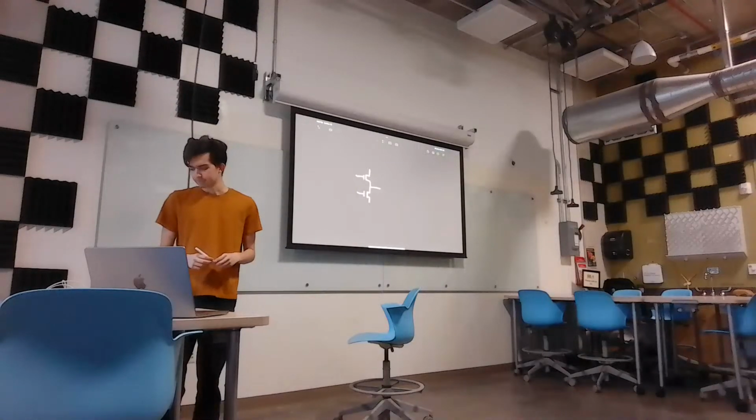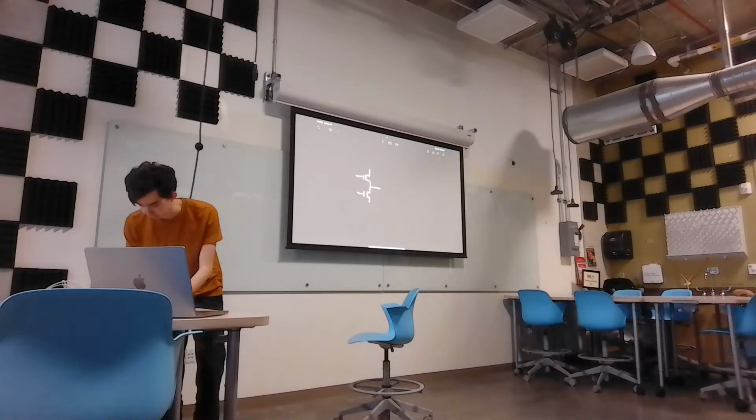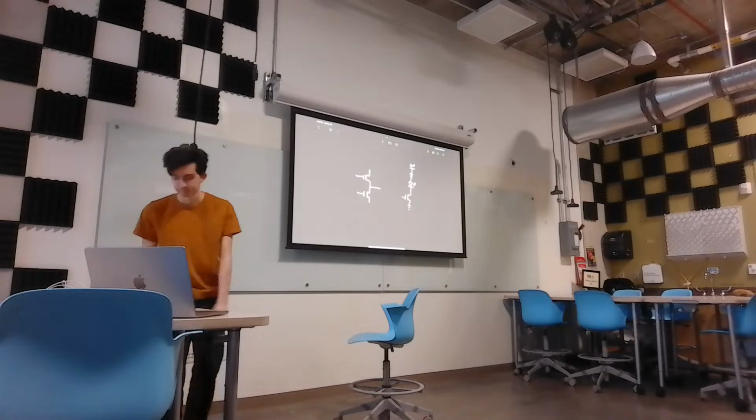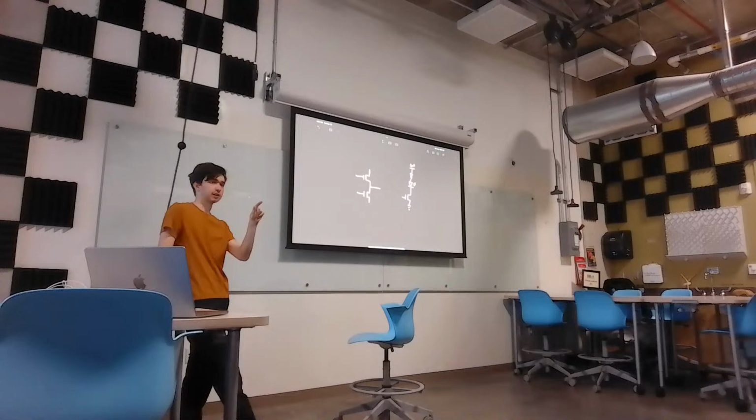I don't know if you guys have ever seen a circuit like this. Let's say we have 3.3 volts, some resistor. Let's do our LED thing again. We put a MOSFET right here. The way you turn a MOSFET on is you put a voltage on its gate.